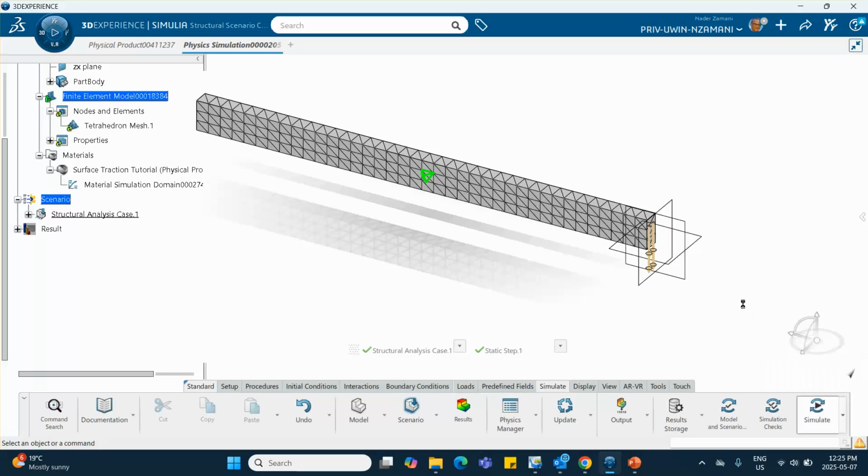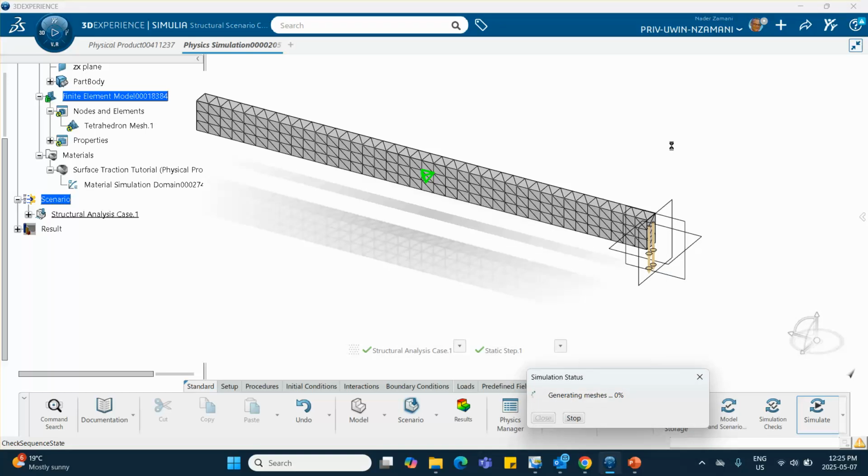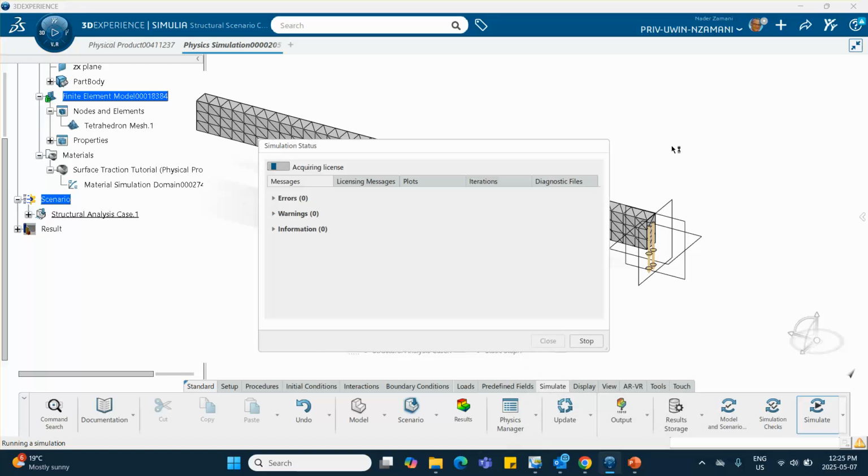So we're going to run it this time. It's a parabolic element. And remember, a minute ago we had 0.06. It was supposed to be roughly 0.0931. Now I'm using parabolic element. And then if necessary, I'm going to refine it further because I didn't like the size of it.